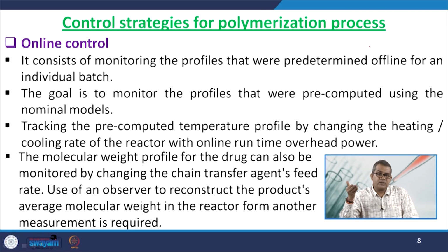If you are handling a catalytic reaction, then there is a chance of affecting the efficacy of that particular reaction, and usually this efficacy works within the domain of a temperature range. So, if it crosses that particular temperature range, then the efficiency of that reaction or the conversion of the reaction mass is usually adversely affected.